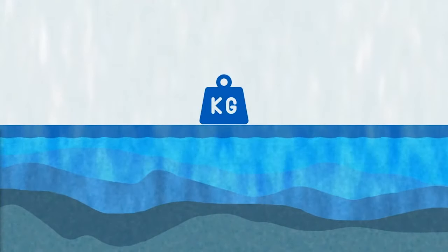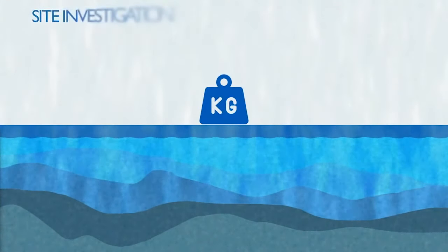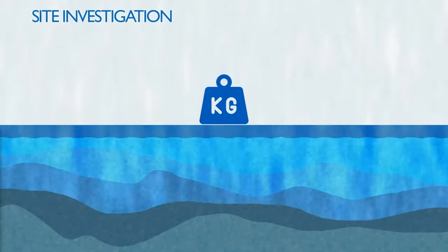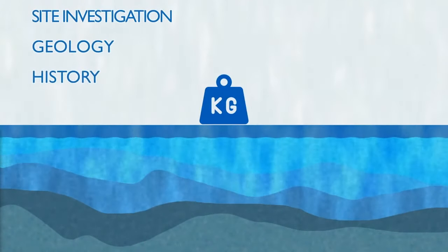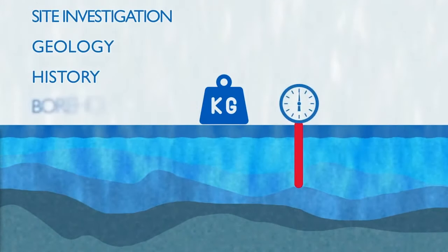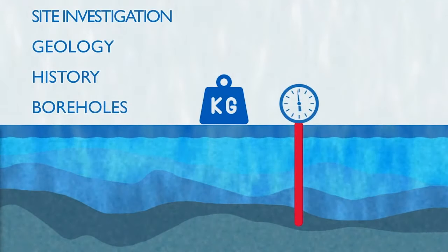Generally speaking, these issues can be determined by conducting what is called a site investigation report, which looks at the underlying geology of the site and any historical uses. It may also include borehole readings to measure the presence of any gases.